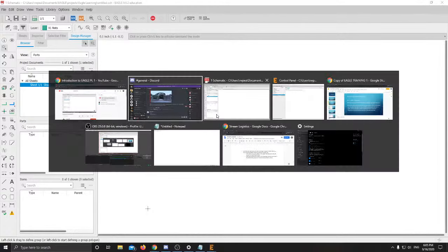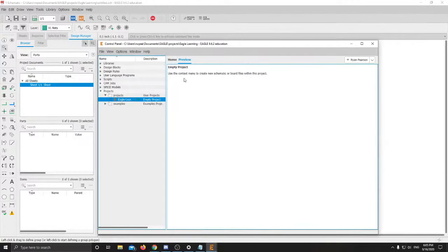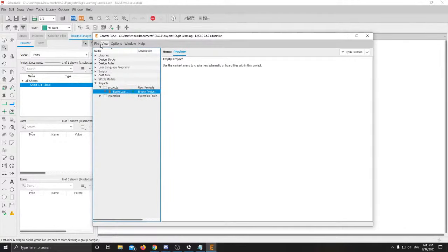So Rohan, after naming the project in this menu here, I went ahead and did File, New, Schematic. It's this one right here, and I'll leave this up for a second. Once you click that, you should see the window that's behind this sort of Eagle menu.